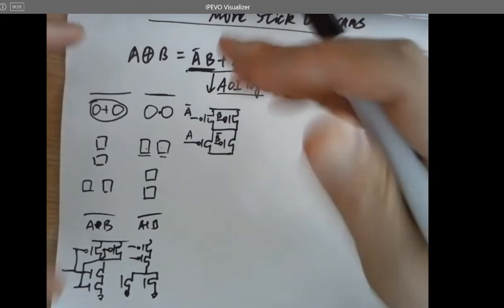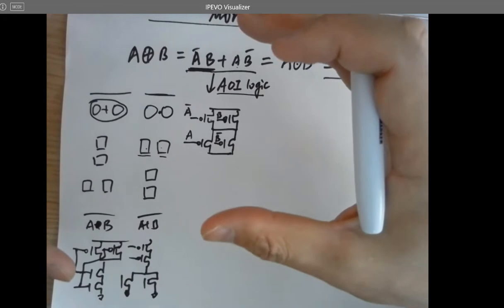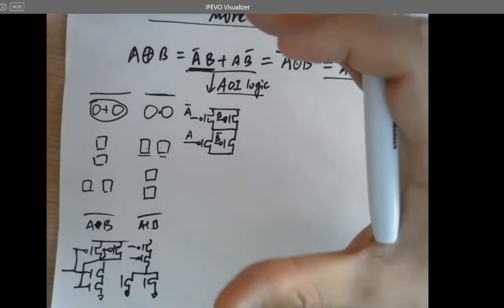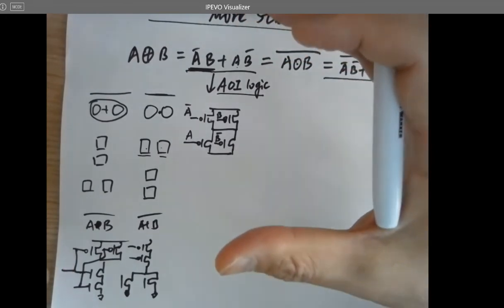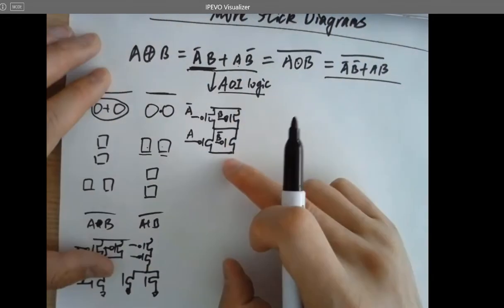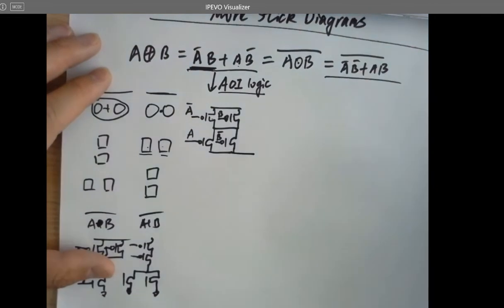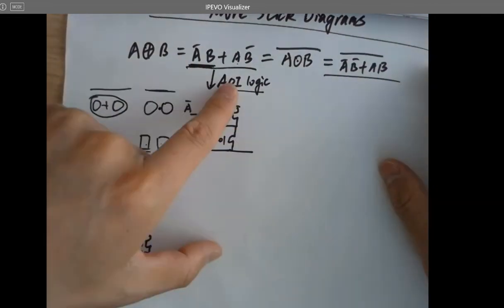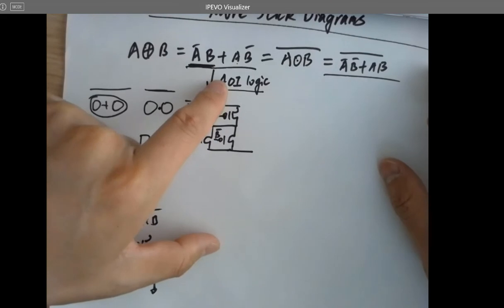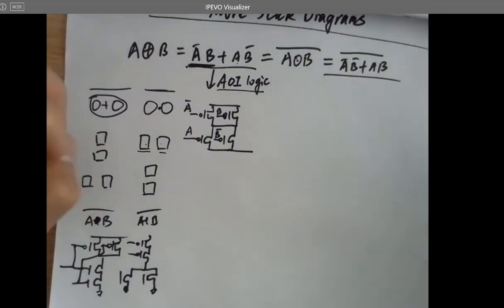Just remember this AOI logic procedure, how we are doing this. It's going to simplify the design procedure for the future when you are designing the circuit. So now we are done for the PMOSes. The PMOSes are pulling this output to VDD. So we are done with the VDD part. We're also done with one output for the truth table. Now let's do the NMOS.